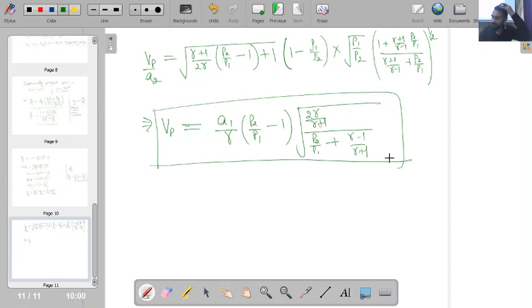Because we have a shock wave, when a shock wave is moving, how much velocity it imparts to the fluid medium through which it has passed, that we are now able to calculate. It is a function of P2 by P1, which is important because it governs the strength of the shock wave. Second parameter is gamma, which is specific to a fluid medium. And the third important parameter is A1, the speed of sound in the upstream stagnant fluid medium through which the shock wave is passing and imparting the mass motion. Okay, this is one point.